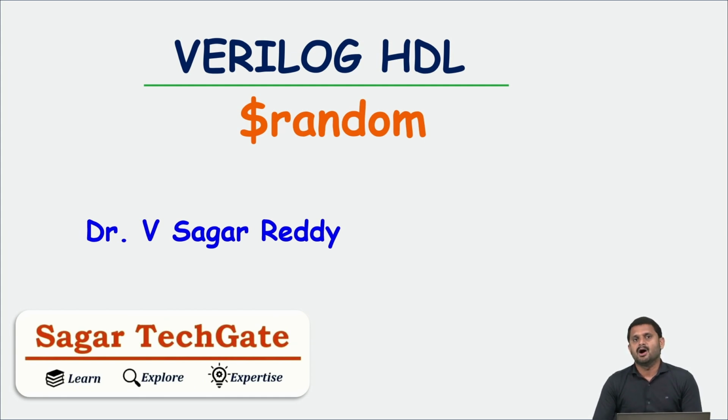So we saw how $random can be used to generate signed random values for simulation, and how to limit the range using a modulus operator. We also explored $urandom_range, which is a safer and more flexible option in SystemVerilog to generate a random number within a specific positive range.